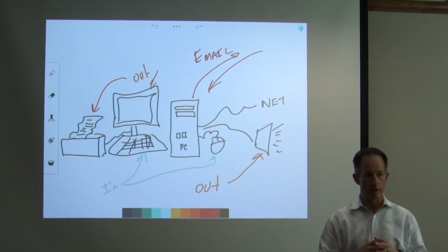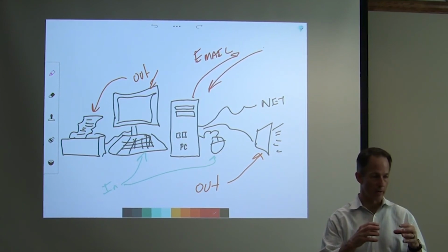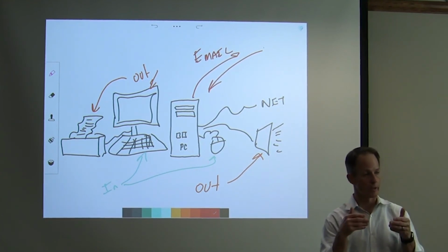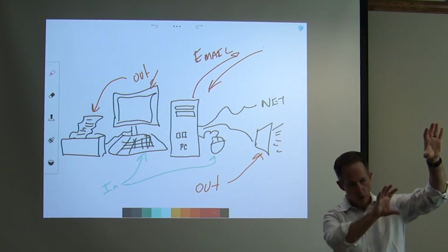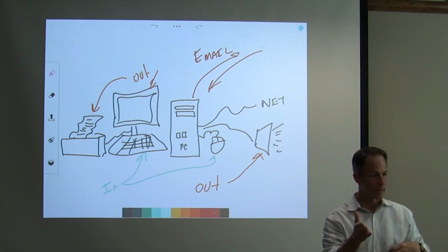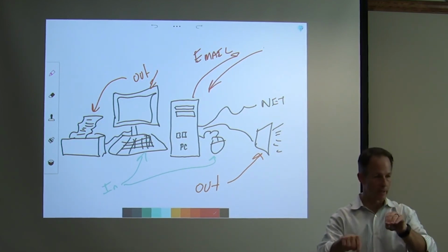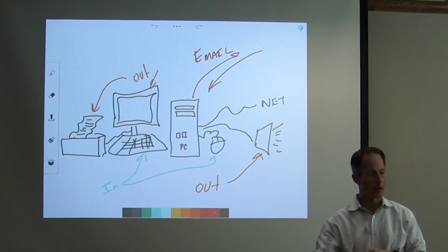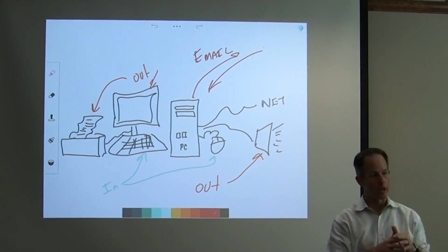Not necessarily. Orange has to do with a fault. When you see that orangey color, not the bright yellow, it typically means that the point you're looking at, especially on the supervisor, so we're way up here on the supervisor, we've got a Jace here, and then the device down here, somewhere in that line of bringing that point along, we have gotten corrupted. In other words, we're looking for a point, but it can't find it in the end device, or it can't find it in the Jace. When there is a mismatch of naming, or if somebody renames something way down on the bottom end and it doesn't get renamed all the way up, you'll get an orange.